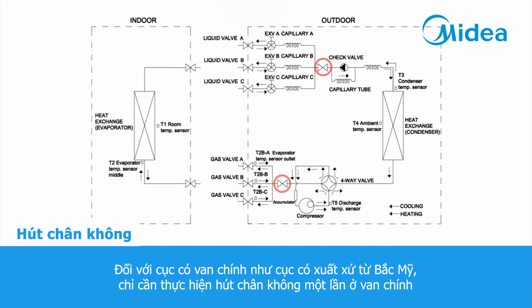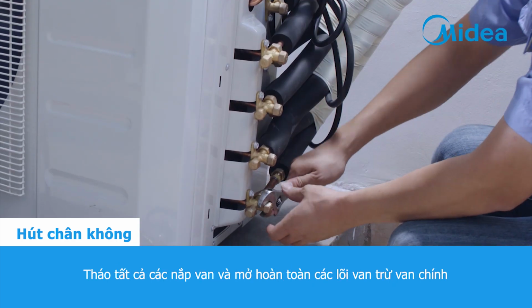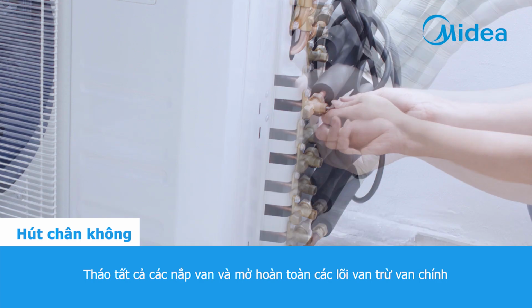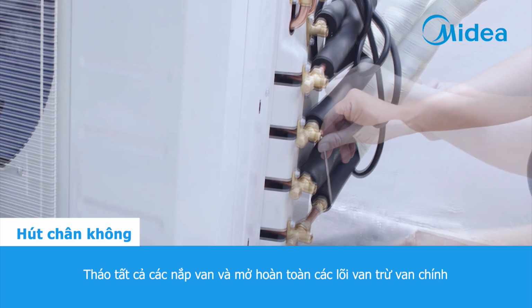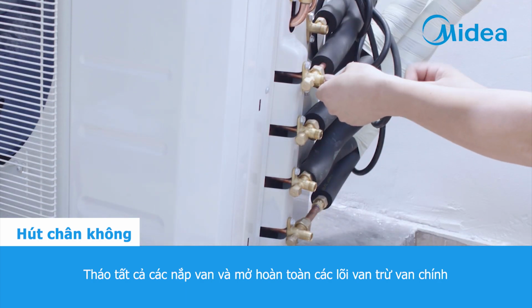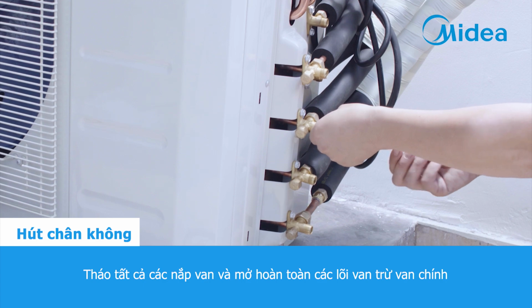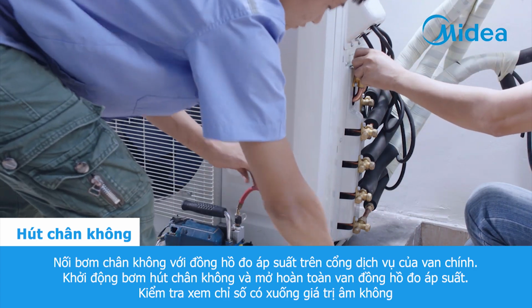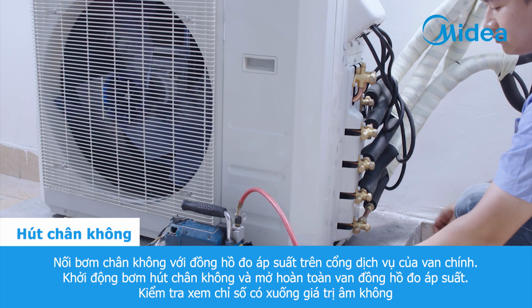For the units with master valves, like North American units, vacuum work needs to be only done once on the master valves. Remove all the valve caps and fully open the cores of all valves except for master valves. Connect the vacuum pump and pressure gauge on the service port of master valve.